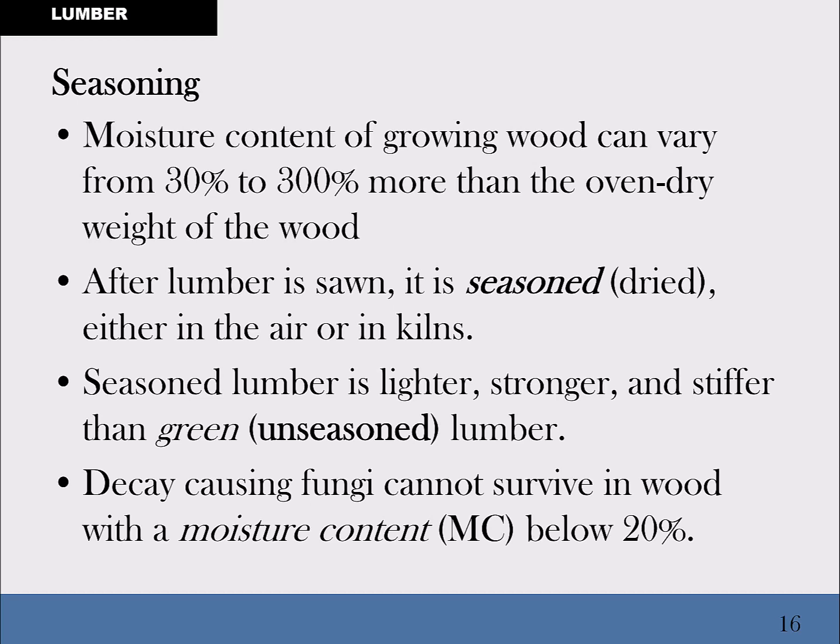So here's the thing. When you've got moisture in your lumber, fungi can grow in it. Termites can eat it up. They need moisture. The soft palates of the termites just can't chew that hard, dry lumber. Now, some termites, like the Formosan termite, bring their own water with them, so they can take a dry piece of wood. So you really have to be on guard for some termites more than others.